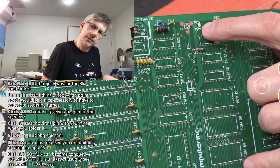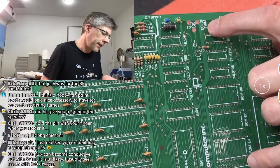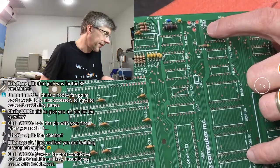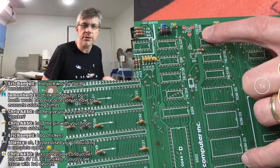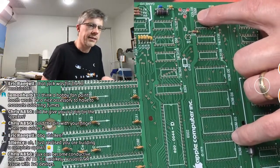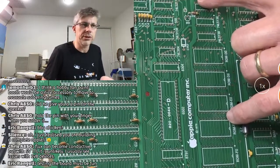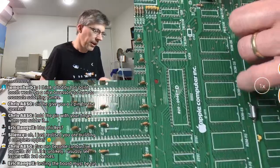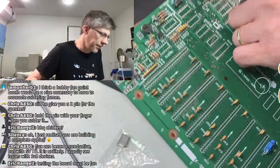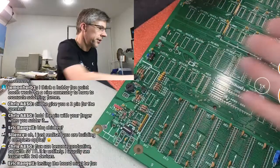So I'm not even 100% sure why they made this like a variable component back in the day, but basically I assume you could adjust the color trim in case your TV maybe was off. But at least in most later models, that color trim pot was actually sealed into position or soldered into position, and so in Henry's kit, he doesn't even give you that little pot there. He just gives you a capacitor to put across it, and so we'll go ahead and do that now.